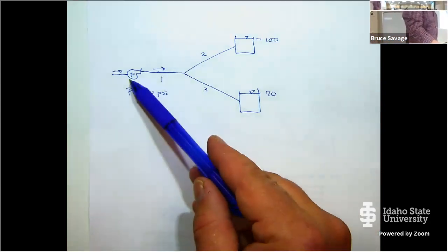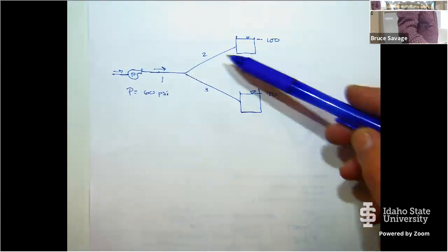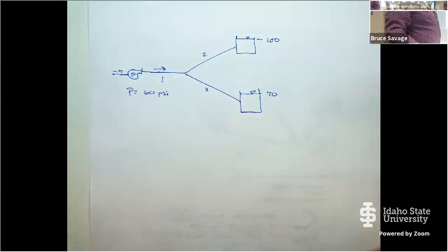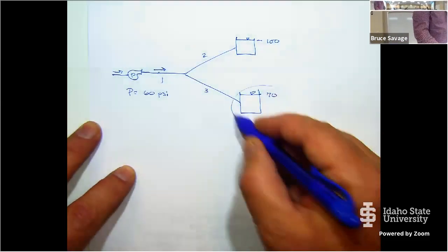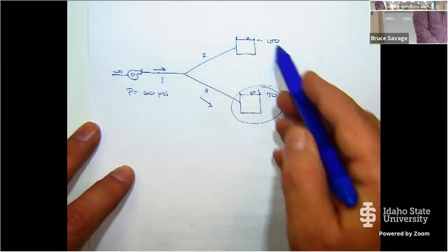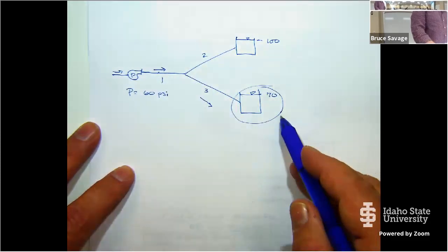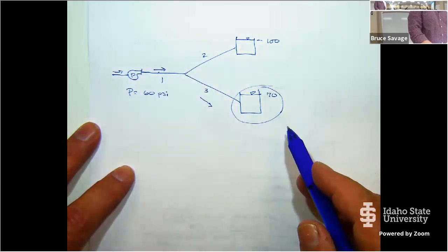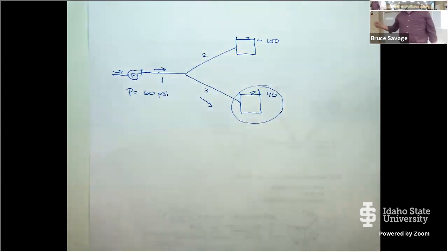Okay, so reservoir, pumping water along pipe 1. 2 and 3, we don't know exactly what's going on, but once again, we know that this is the lowest. Okay, so we're definitely going to have flow going this way. Is it possible for the flow in pipe 2 to come down and join up with the pump and go down to 3? Sure, it is. Or it could be possible that that pump is supplying both reservoirs, all right?